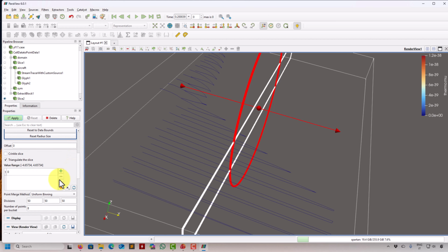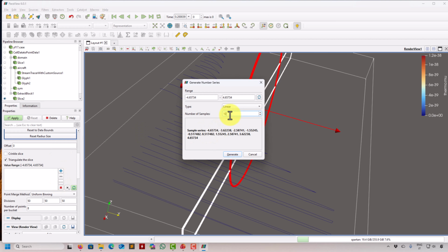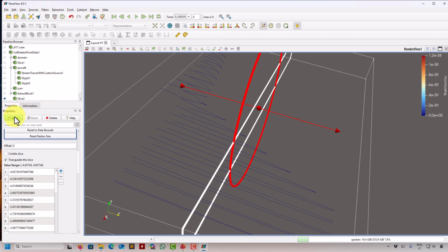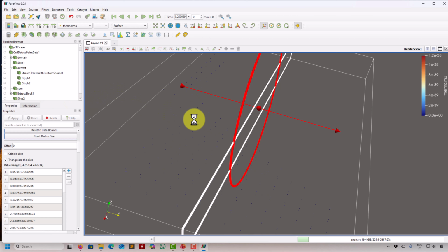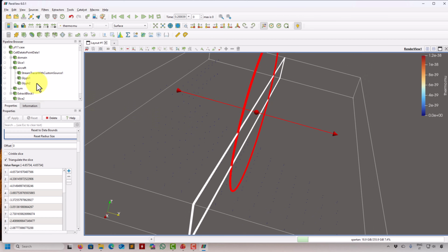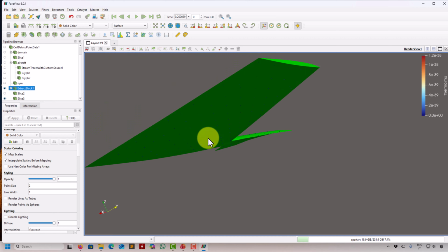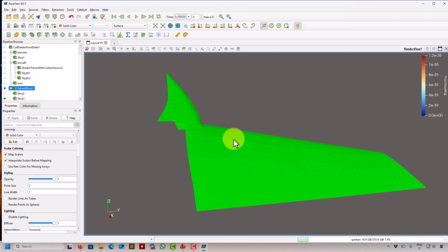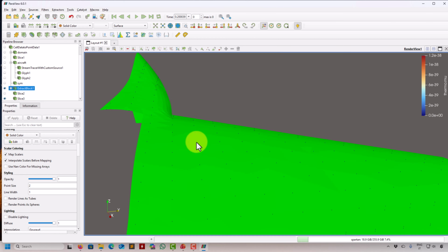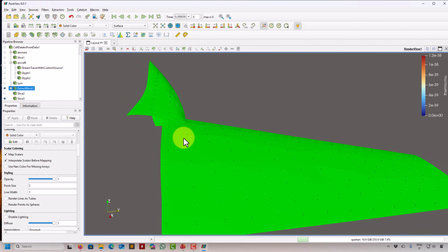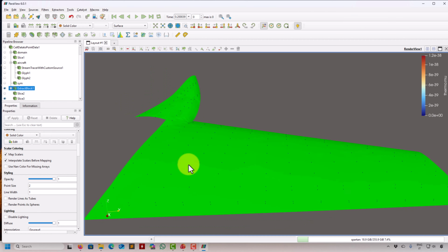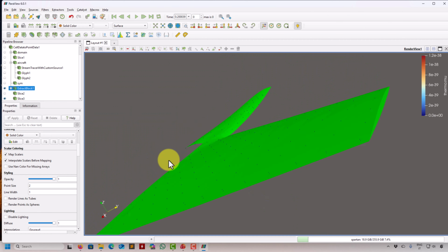And let me create 30 slices there, that are intersecting the previous lines that we get from the previous slicing. And at the end, what we're going to get, well, you see it there. These points uniformly distributed. And now you get the idea that we can release the streamlines from these points. Very nice trick, okay? I use it very often.